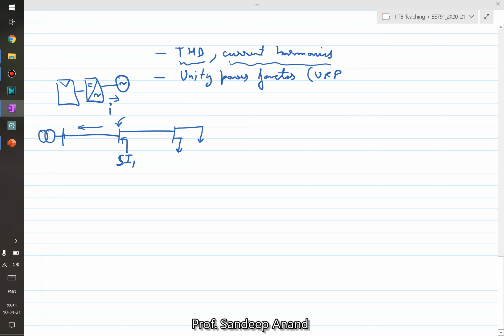For instance, if there is a certain load and the inverter starts drawing a lot of reactive power, then one may have to install additional capacitor banks. Therefore, initially it was asked that all the inverters must stick to feeding power at unity power factor, so that it does not create any additional voltage drop because of the reactive power they may start drawing.